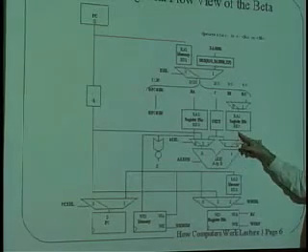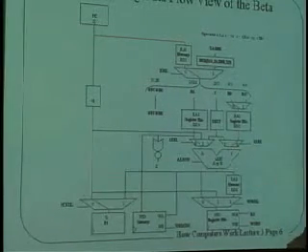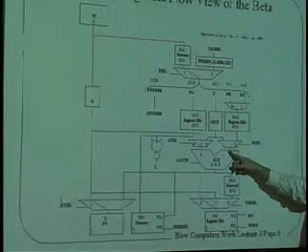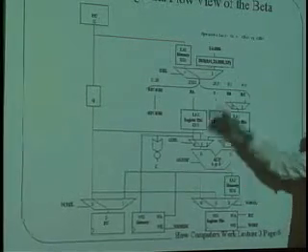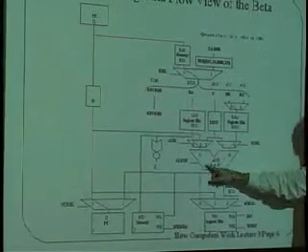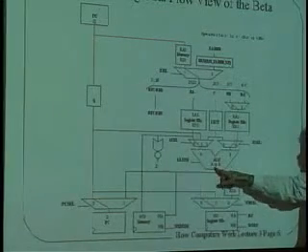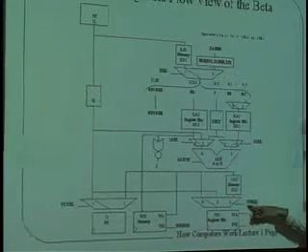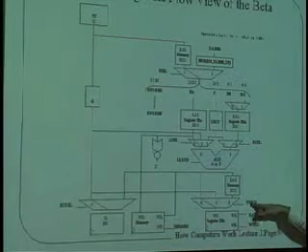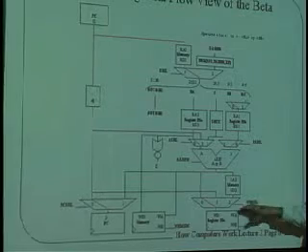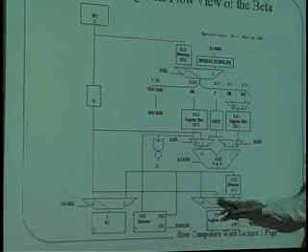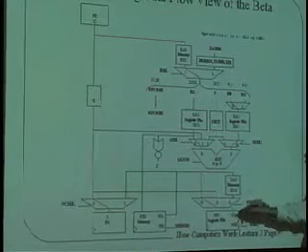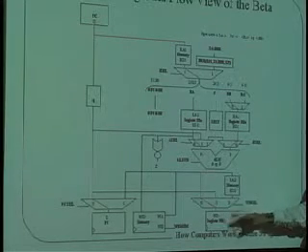And this one's going to choose the output of this portal to that same register file. That's going to go into B. The function that's going to go in here is going to be whatever operation we're trying to do, be it add or subtract or what have you. The ALU will do the calculation having to do with that function. The result will come down here and go down to this selector now, which is called the write data selector, WDSEL, which is used to decide which source of data we should use for the register file where we're going to be doing a write.